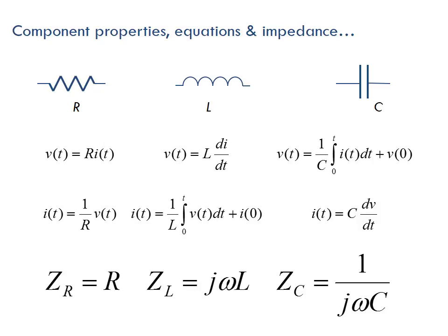And then finally, on the right, we have capacitors. Our voltage equation for a capacitor is 1 over c, the integral of I of t dt, plus whatever the initial voltage is, because a capacitor is storing charge. There's a great lab that we're doing in Physics 2, which is the time constant of charging a capacitor in an RC circuit, a resistor and capacitor circuit. We can look at how to do that in this chapter and why it works at a more deep and interesting and actually beautiful mathematical level.